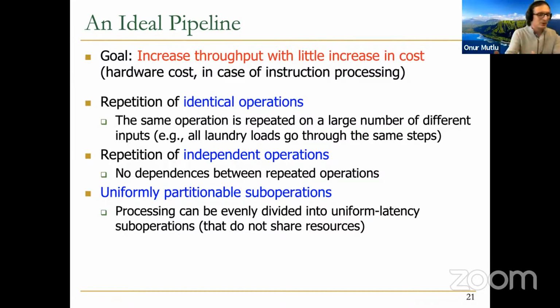Well, in the real world, it's a clock cycle, right? Basically, for example, if your washing takes 15 minutes, but you're waiting for the entire 30 minutes, you wasted half of that pipeline stage or clock cycle. And we're going to see that this is real in instruction pipelines. Now, this may not be a problem in a laundry pipeline, but you need to be careful. Again, you need to balance the different stages of the pipeline nicely. Whenever you have a clocked, synchronous system, where the pipeline stages take exactly the same amount of cycle time, you will have this sort of problem. And we will see this in a little bit.